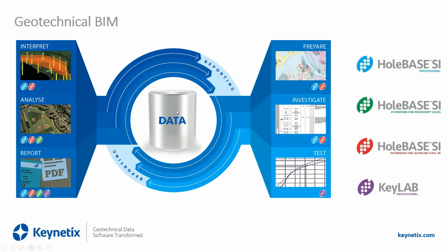You can use it to schedule tests for labs, and we actually write lab management software as well, so your geotechnical labs can use our software, send it all back to HoleBASE, so you've got all the data being managed. But then we make that data available in the geotechnical module, or we have a big brother for it called the HoleBASE SI extension for Civil 3D that allows you to do a few more things, and that data is seamlessly available inside of AutoCAD Civil 3D. Update the data in HoleBASE and you update the data inside Civil 3D.